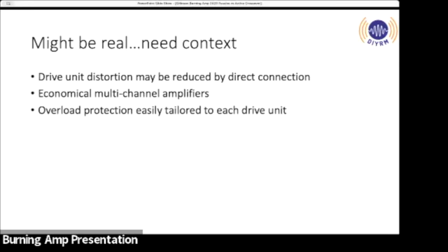This one is pretty real. Overload protection is easily tailored to each drive unit, okay? In a residential setting, nobody does overload protection anyway, right? So for home speakers, nobody does overload protection anyway. It doesn't matter. Voice coil heating will not affect crossover operation. Again, go back to that previous slide that I showed. That 6 watts pink noise was super loud, and voice coil heating didn't. This is theoretically possible, but I would have to make up a contrived test to make it quite audible, right?